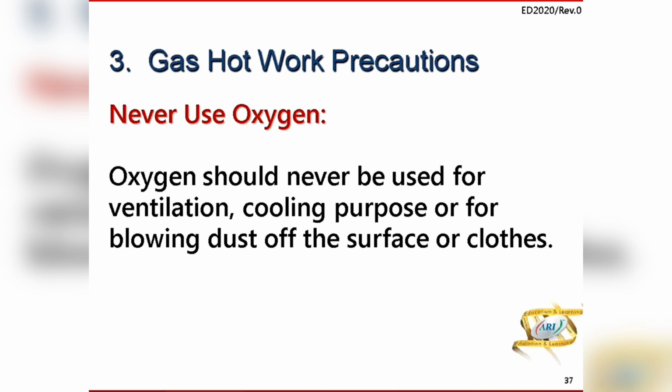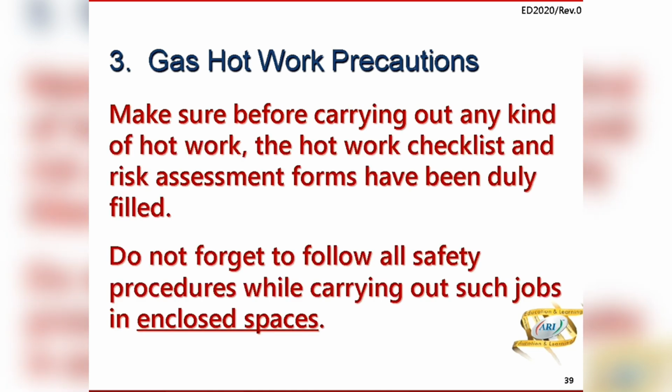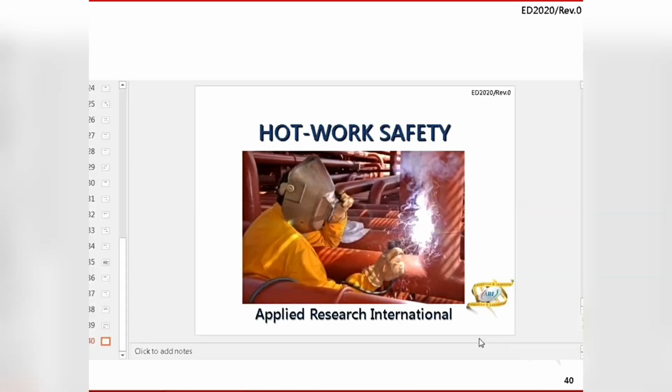Oxygen should never be used for ventilation, cooling purposes, or for blowing dust off the surface or clothes. Discard length of hose which has suffered any flashback, because that hose will be rejected. Make sure that before carrying out any kind of hot work, the hot work checklist and risk assessment form should be duly filled. Do not forget to follow all safety procedures while carrying out such jobs in enclosed spaces. So that was your hot work.